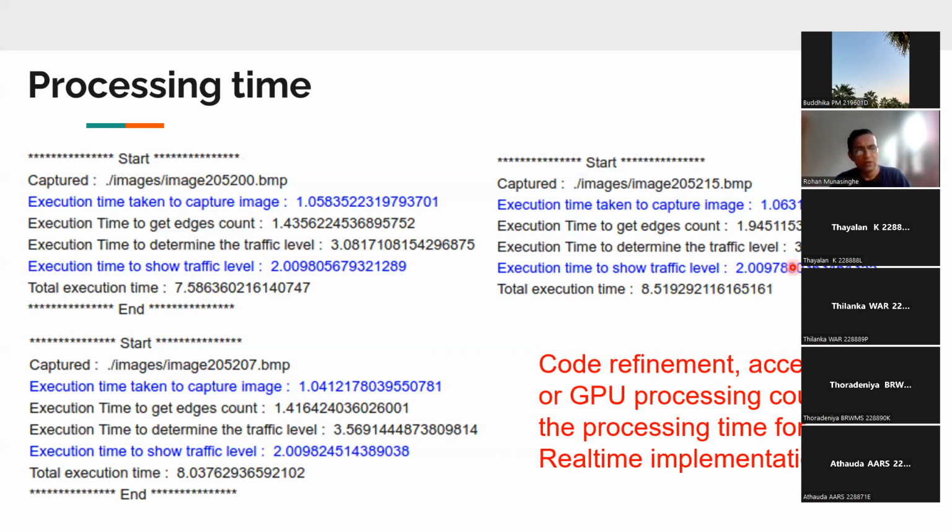So again, I want to emphasize, whatever you see in duplication and other things, it's not actually adaptive control. It is basically synchronizing. Of course, throughput is improving because you don't have to stop at every junction. Once you pass one junction, you can get almost a free ride to some extent. But real performance could be enhanced when you have a propagating model of traffic from one junction. If you have a jam in one junction, that information will also propagate to the other nearby junctions, so their times will also be adaptable according to that.